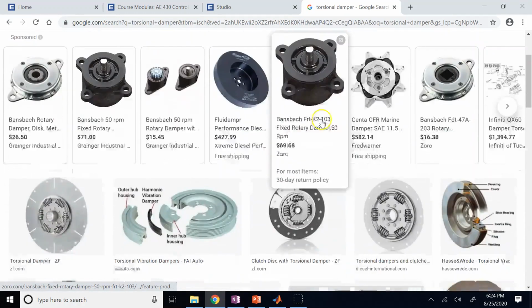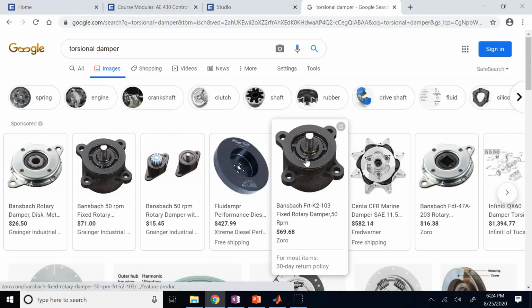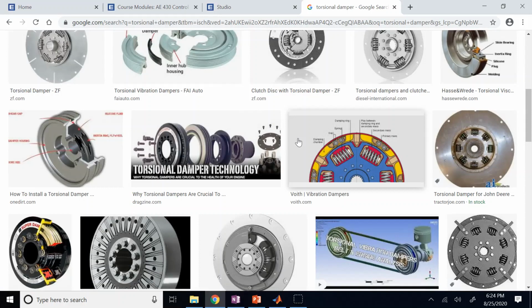There are also some physical ones too, like these, where basically the shaft is directly inside. So it's not like you're just spraying the lubricant on the shaft. The shaft is inside a chamber, and inside the chamber, the object is moving inside the lubricant liquid, and that will basically eat out and damp out the mechanical energy. Okay, right? So that can be a mechanism.